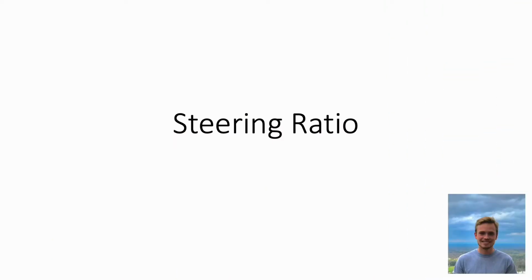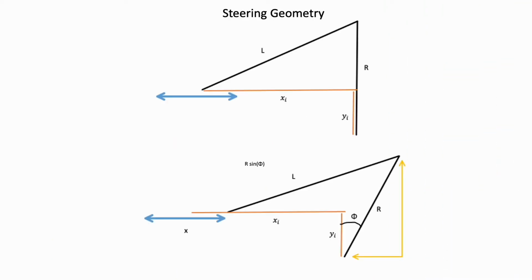In the design process of the Formula vehicle, we needed to determine the steering ratio. After some research, we found some equations to get an approximation for the steering ratio. However, the approximation was only good as long as the angularity in the system was minimal and the tie rod was nearly perpendicular to the steering arm in the top and front views. However, our design does not fit this. With this in mind, we determined that an equation would have to be derived for our specific steering setup.